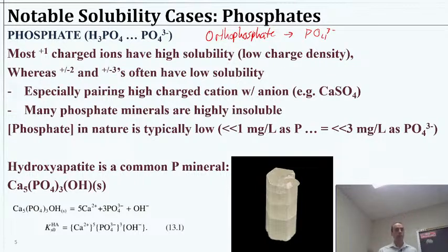If you were to do that, we recognize, like the carbonate system where we have the different forms, the orthophosphate would exist at high pHs, right? So adding it would essentially be adding something that's ready to take up some protons. So if you add it in that form, it'll probably end up at near neutral pH. You'll end up with H2PO4- and maybe HPO4 2-, some combination of those at near neutral pHs.